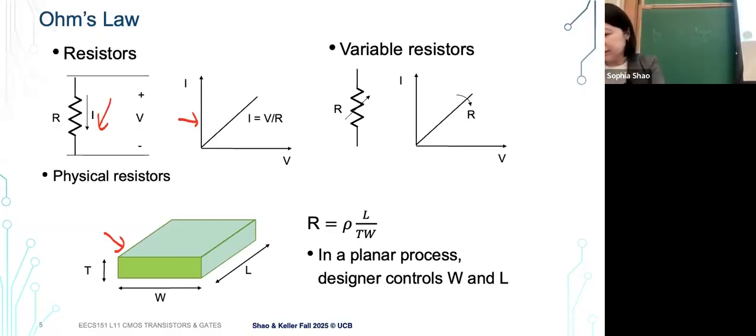If we think about the resistance here, it's related to the resistivity, the material property of the device being used to conduct current, and also to the length of the component. The longer the component, the higher the resistance typically, because the current needs to travel much longer and there are a lot of things that could limit how fast it flows. So the longer the device is, the higher its resistance.